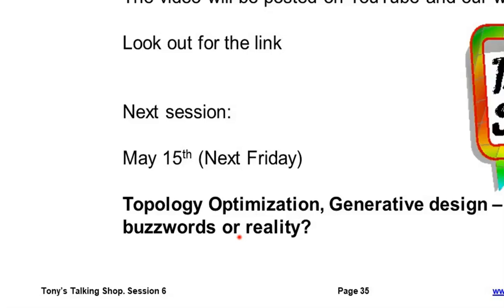No, it's a very good question. We're dealing with very small local regions of plasticity. So the idea is that the overall structure remains predominantly an elastic response. So the idea that if you have a stiffer structure, it's attracting more load, that's generally true. We don't have big regions of local plasticity which are going to change the load path. So that is one of the limitations of the approach. We're talking about a local plastic correction, which is a very, very localized plastic correction.